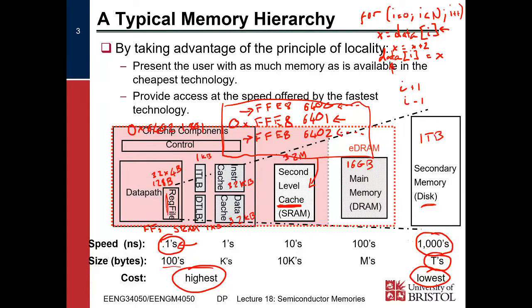But that's only possible because we've got smaller transistors. The same thing here: we can only now incorporate the second level cache onto our chip because our transistors and our memory cells are smaller, so we've got space for it. And it's worth it in terms of keeping the memory as close to the physical processor as possible.